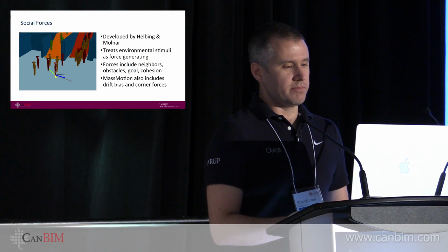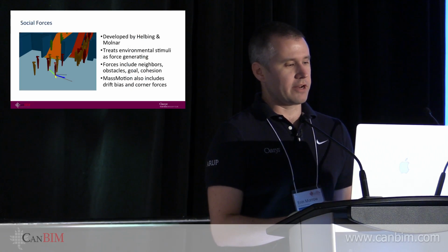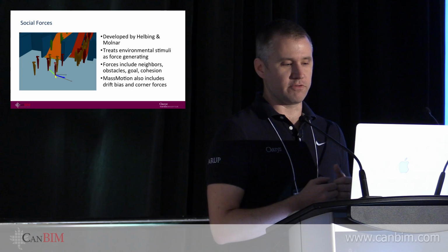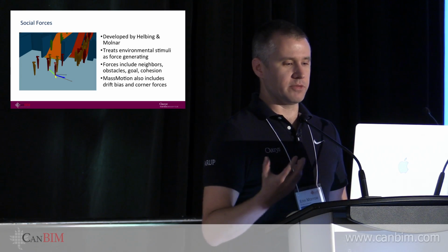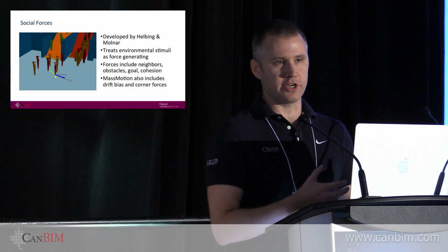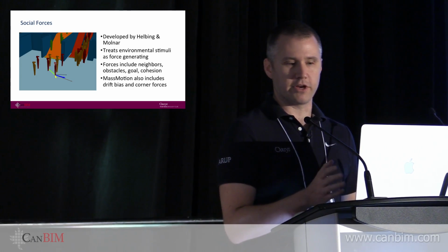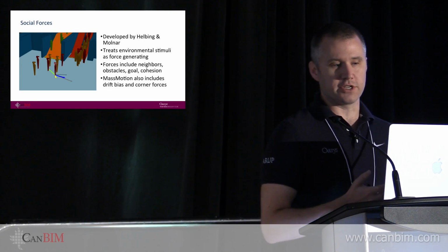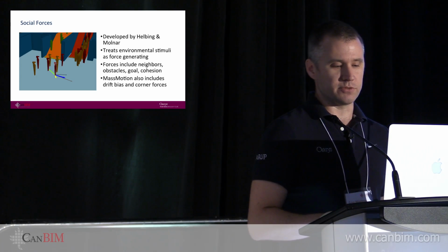There's a mathematical formula called social forces, which basically describes the way that people reflexively respond to their environment. So the people around them exert a sort of repelling force, as do obstacles, but they're also trying to achieve local goals, like getting to a doorway or a stairway, and that draws them in a particular direction. And all these different forces get summed up and govern the next step that the agents will take.